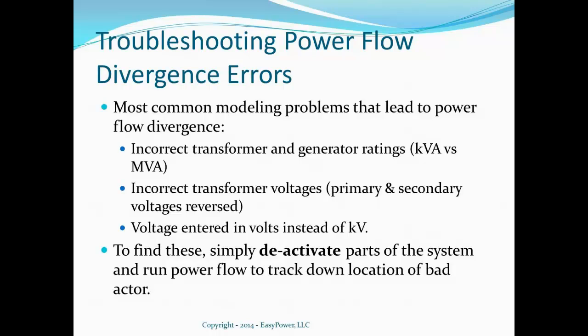If you have a big model and you want to track those down, you can start deactivating parts of your system until you get the power flow to run, then you can gradually narrow down where the problems are.